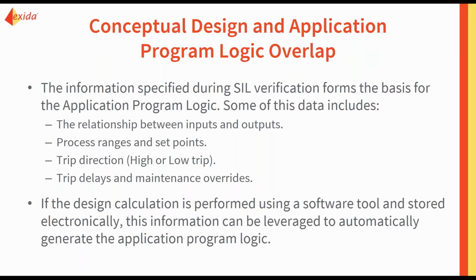Often what we do these days is you have your SIL calculation and you have some outputs. Most of the time this is going to be in the form of a cause and effects matrix, and somebody will print out that report and they'll take it and they'll interpret it to manually configure the safety logic. And this is a perfectly fine way to do things, but to be able to leverage the inputs into your SIL verification calculation in your design SRS, you're not only going to save time, but it's going to drive consistency.